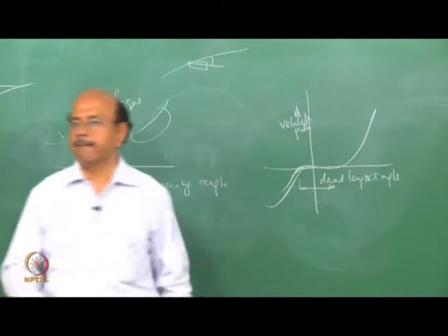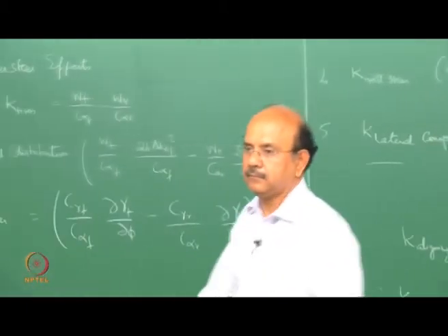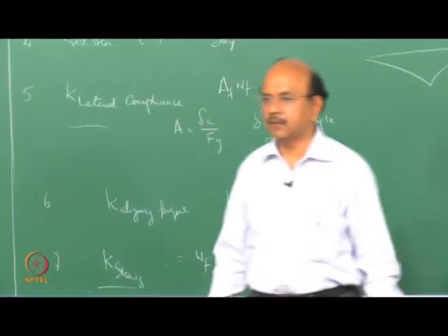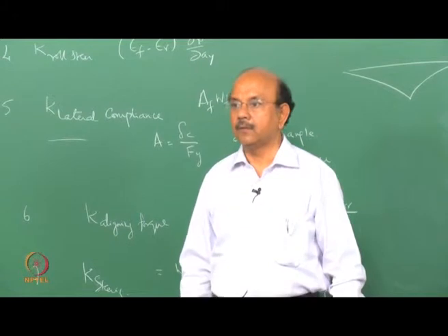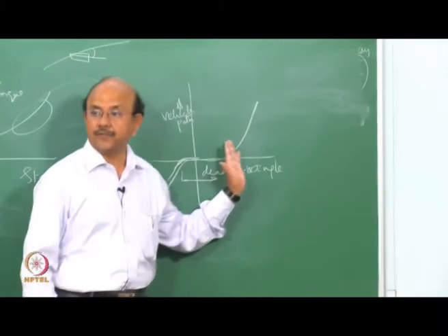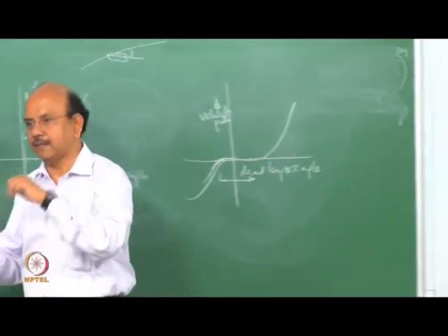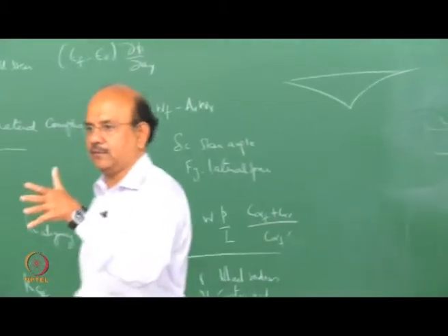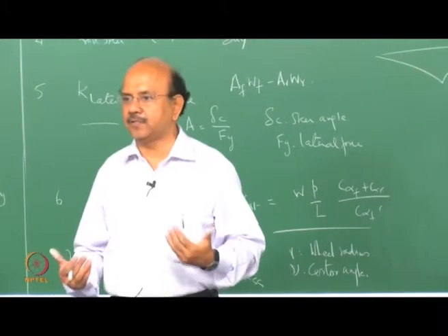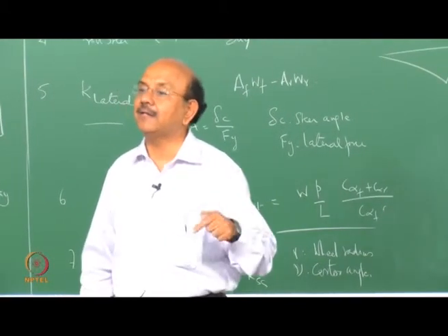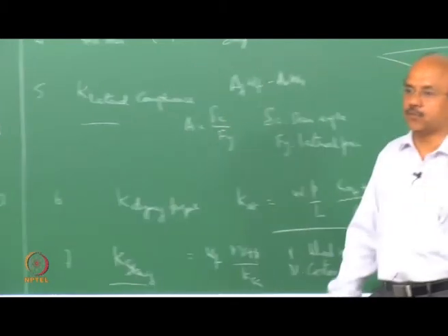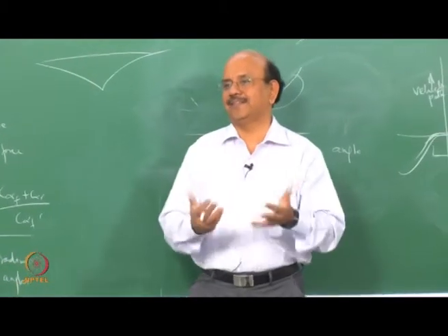Clear? So you said the reason for having that dead zone was so that disturbances wouldn't cause changes in the vehicle path. But what if the disturbance happened when your steering angle is not at the dead zone? No, that's correct. If it is off, that's what is called off center. If it is off center and there are disturbances, you have to control, no doubt about it. But when you are going straight, I do not want the disturbances to be affecting. That directly impacts your fatigue, right? Because if you keep on turning when you go straight, the fun is lost.